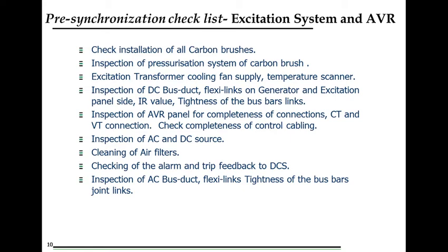The excitation transformer is there. The temperature of the transformer should be normal and the cooling system of the transformer should be healthy. Then we must see that the cleaning air filters are healthy. Inspection of the AC duct and flexi link, as we have checked in the generator case. In this also we need to check that they are healthy.